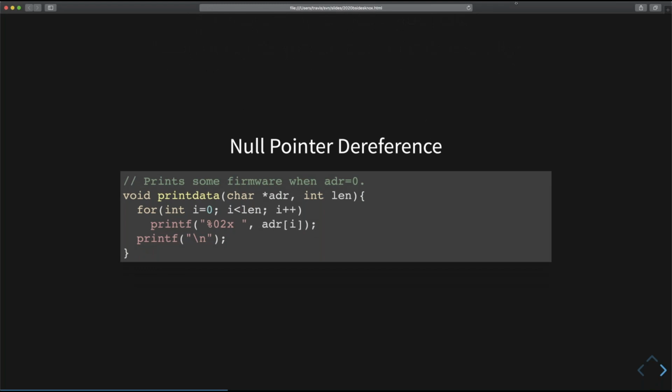When I'm hunting for a bootloader vulnerability, this is one of my favorite tricks that would never work on a PC. On a PC, you have something called a guard page at address 0. The purpose of the guard page is that if you ever have a null pointer, meaning that the pointer is 0, and you try to read from address 0, the guard page will trap and inform the operating system, and the operating system will kill your process. The reason for that is that very often you forget to initialize something, or you try to allocate a buffer when you're out of memory, or any number of things, and you're stuck.